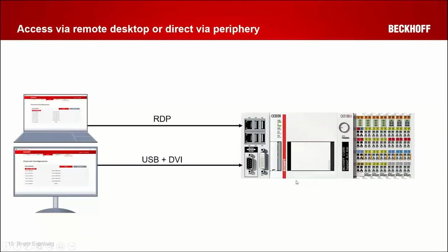Sometimes we are not able to have an engineering notebook with TwinCAT installed. So we have a second possibility to configure a system. We are using PC-based control features to get everything in one system. The steps are pretty much the same. First, we have to build up our field bus. Second, we have to wire the sensors.